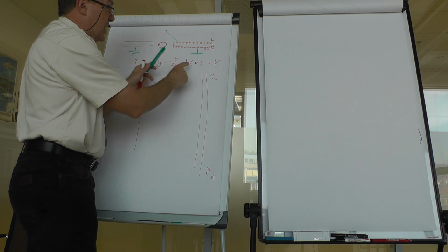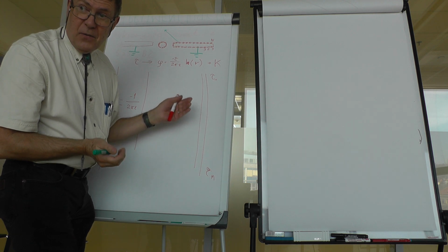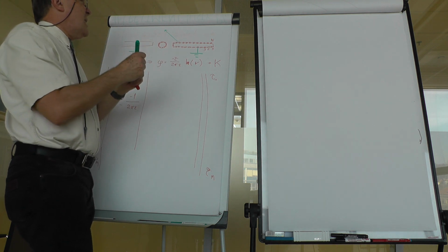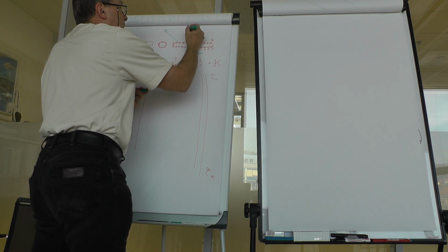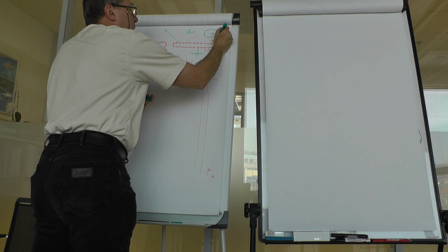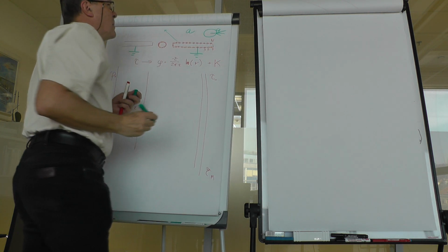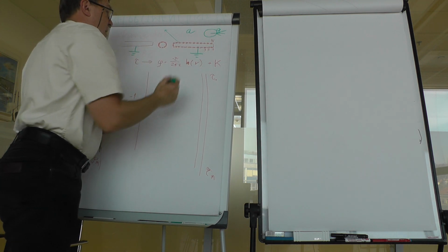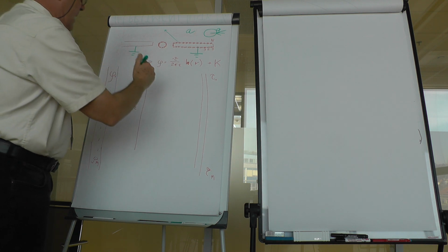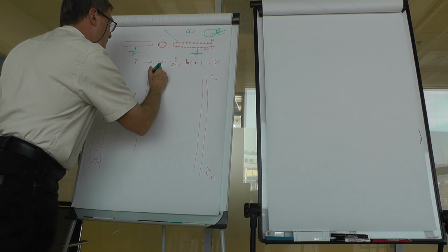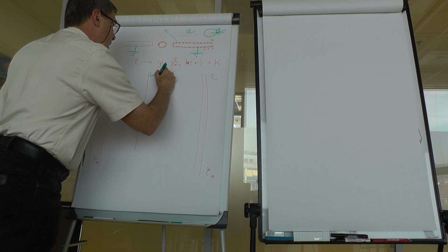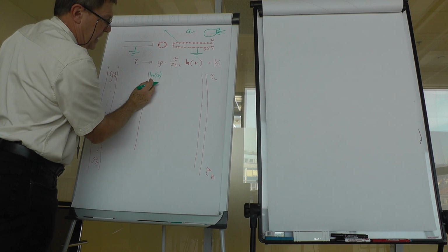How far is the surface of a wire from its center? That's the radius of the wire. So I choose some radius for the wire. Let's call it A. So we have wires of radius A. And this would mean that here we would have the logarithm of A, and that would be on the diagonal.